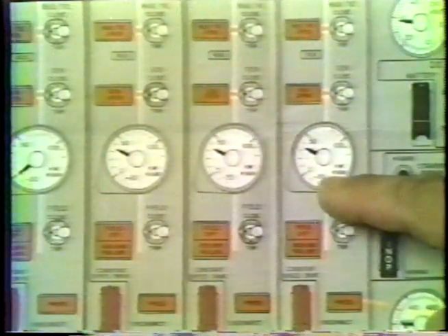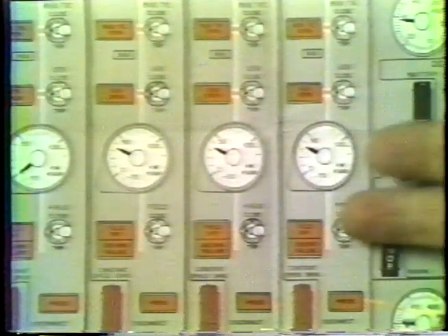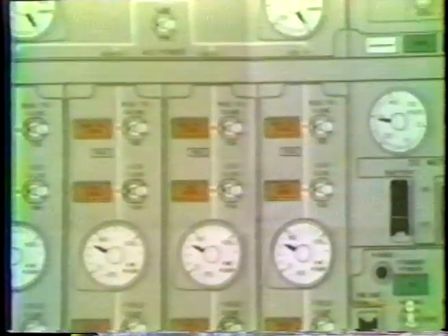If they get out of balance too far, automatic protection will isolate that generator by opening the bus tie. If opening the bus tie represents a further electrical problem with the generator, it may cause the field to trip, the generator breaker to trip, and the bus tie to automatically close again.